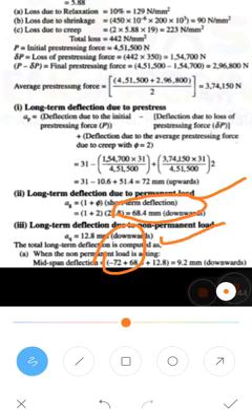So altogether you add it, and if you sum you get 9.2 mm deflection in the downward direction. Okay, so this is for when the non-permanent load is acting, at the mid section. So that is for the downward deflection.